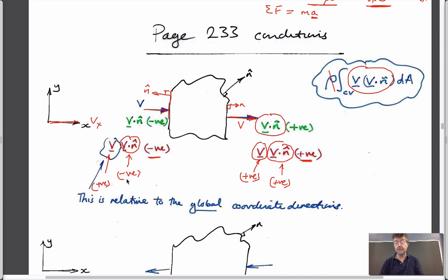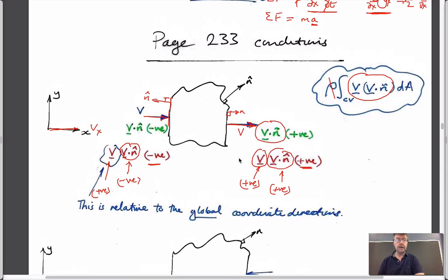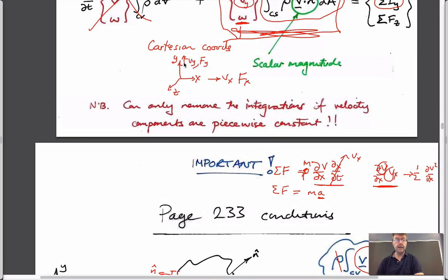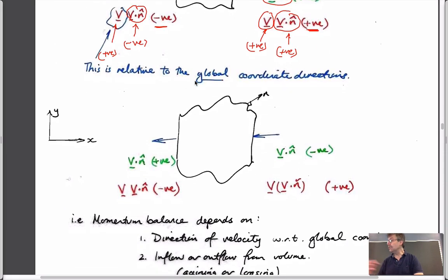When you have one positive and one negative, the result is negative. If you do that, you don't have to care about the velocities being vector quantities; it can just be the scalar magnitude. That is really what you have to get into your head about the sign convention. The velocities in x and the forces in x have to be aligned positively in the direction of the coordinate system, but the into or out of across the boundary magnitudes still retain the positive outwards and negative inflow conditions.